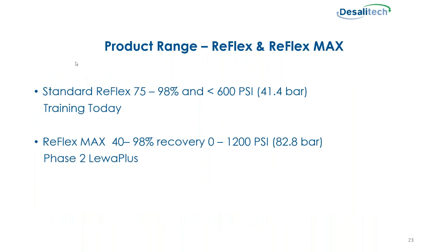So Desalitech has two standard products. The standard Reflex, we call it, Reflex stands for reliability and flexibility. The recovery range is 75 to 98%, and the pressure has to be less than 600 psi or 41 bar. So the current module in LewaPlus is the standard Reflex.